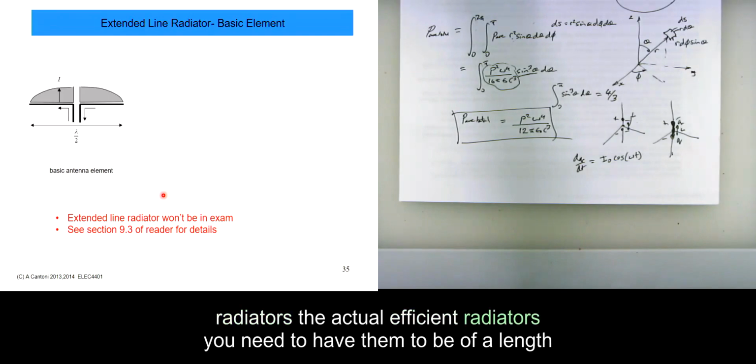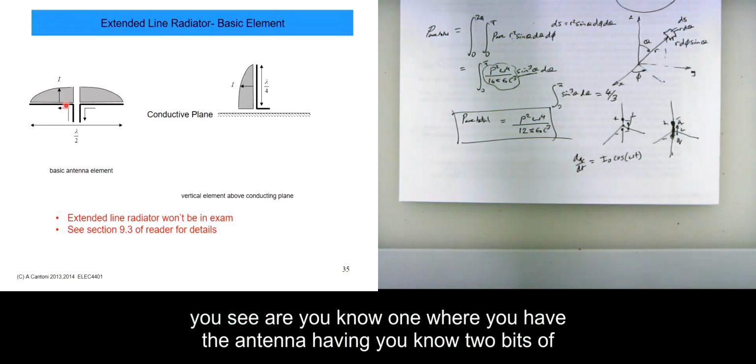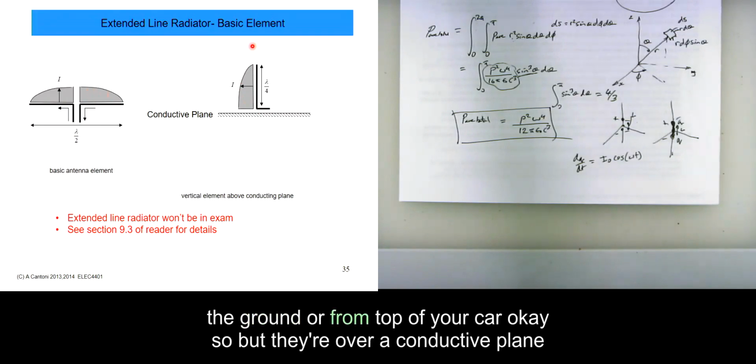For efficient radiators, you need them to be of a length comparable to the wavelength. The two typical ones that you see: one where the antenna has two bits of lambda over 4 to make a half wavelength antenna, looking something like this. You also often see antennas with just lambda over 4 sticking up from the ground or from the top of your car, but they're over a conductive plane.